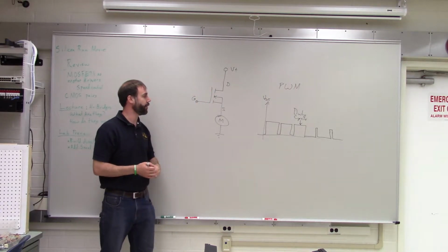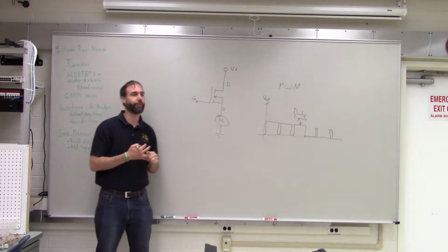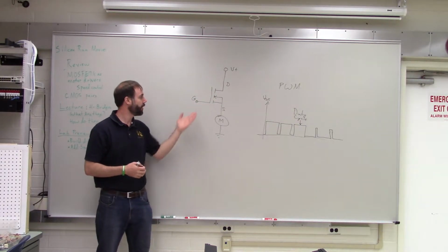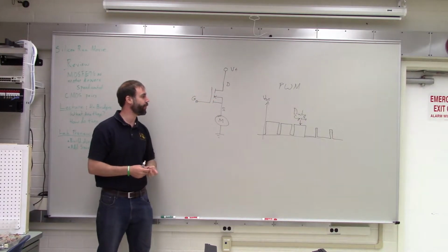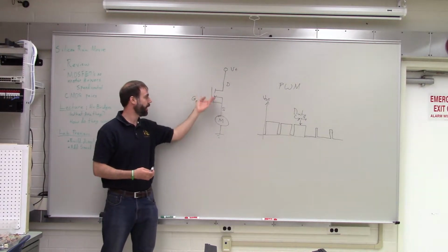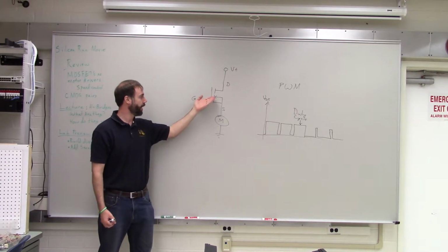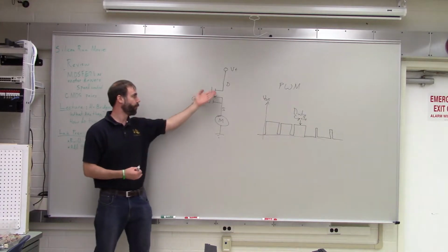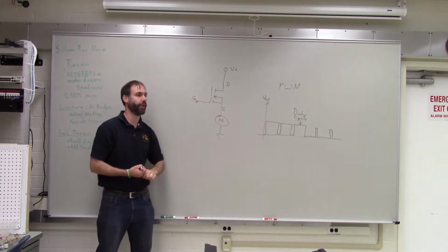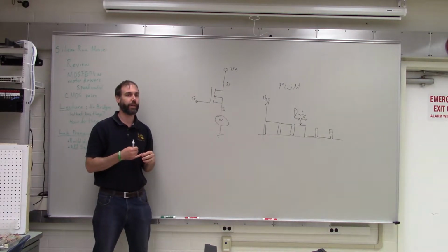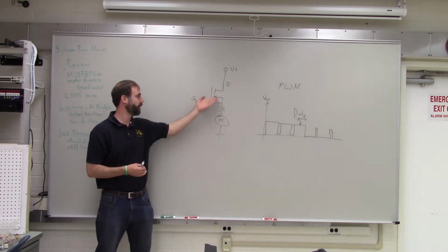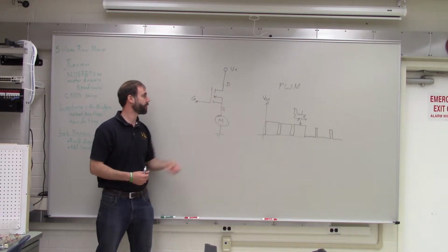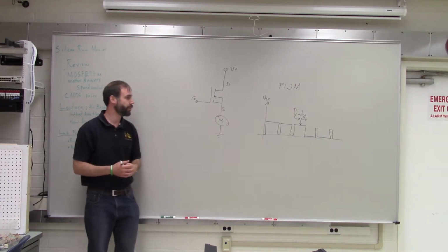The transistor is very efficient when it's completely on or completely off, right? It uses very little power when it's completely on or completely off. When it's sort of halfway in between, it has a sort of middle-of-the-road resistance, which means that it has voltage across it and current flowing through it. And you guys remember from Watt's law that voltage times current is power. So if you've got voltage and current on this MOSFET, then it starts to use up power.